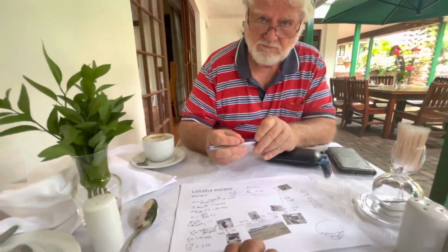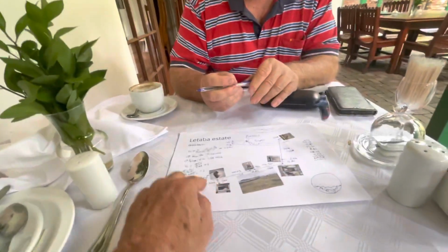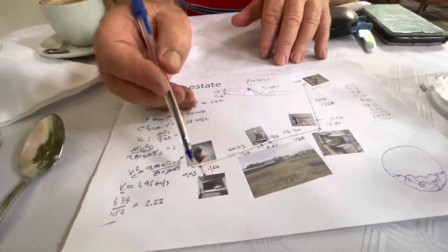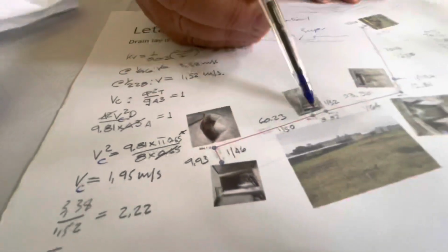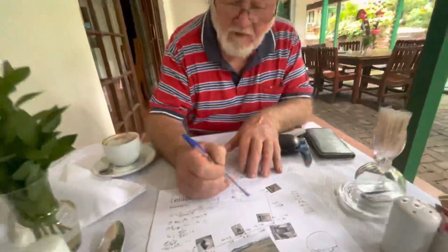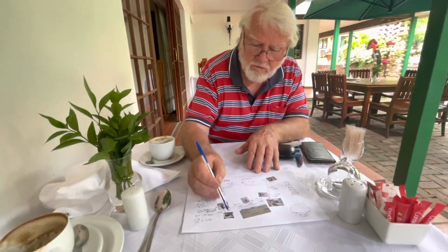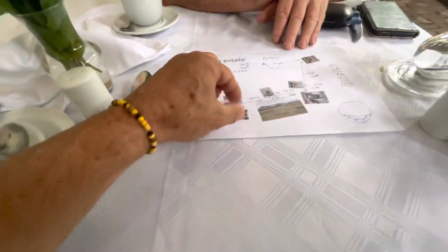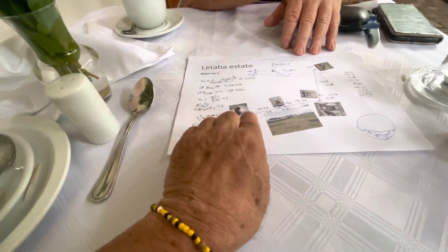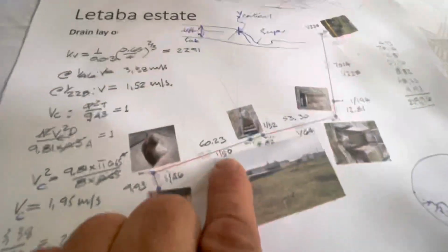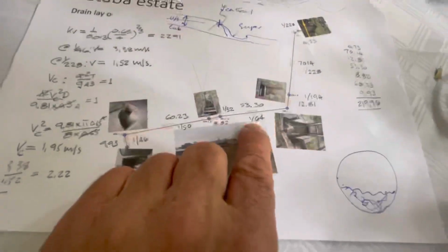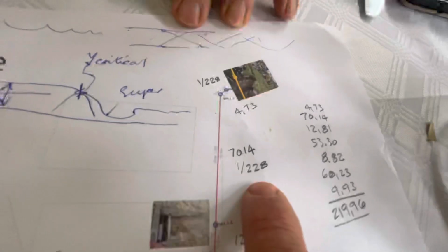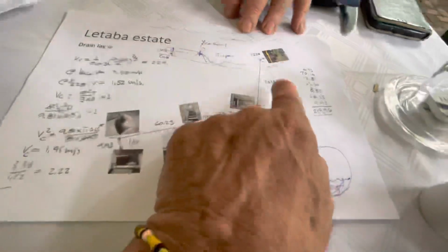And your suggestion to our team is always to put these onto a Google Earth. If you can put this on a Google Earth, and then you can superimpose this line on it, and then you can have little inserts of the particular critical places, to show your client that you've understood this is a 1 in 46 fall, that's a 1 in 50 fall. That's a 1 in 64, so it's getting flatter. 1 in 94, 1 in 228, so it's getting flatter and flatter, and so the velocity reduces.